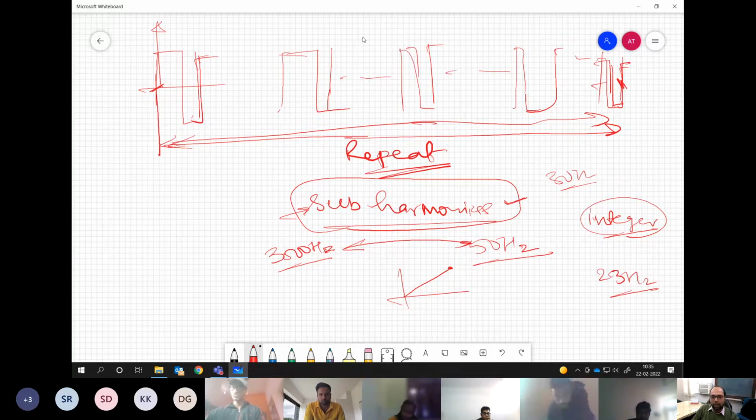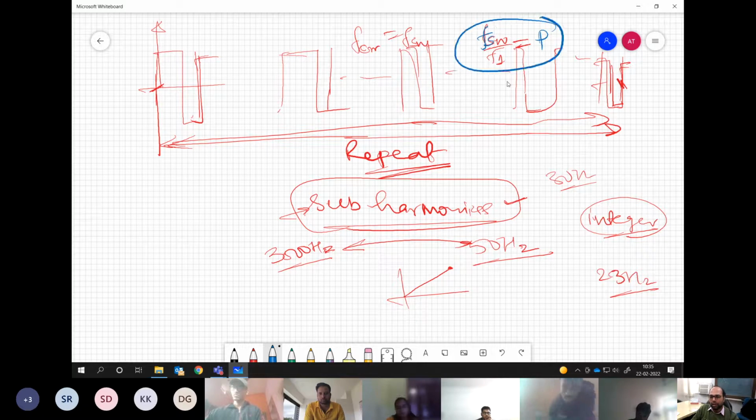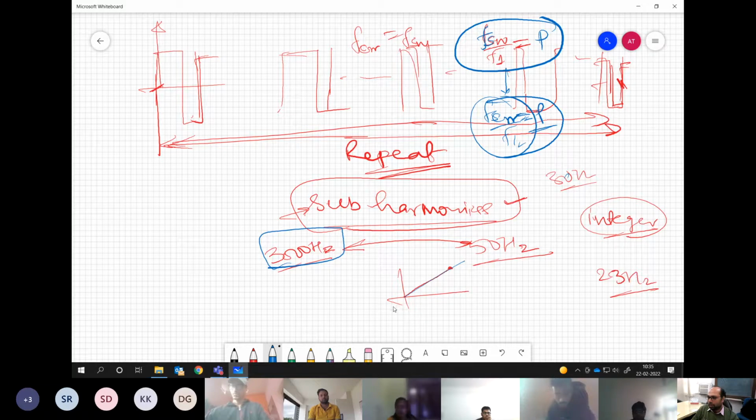So what is this ratio called, when we know that carrier frequency is the same as switching frequency? This ratio is called some name we have given, right? Sir, pulse number. Yes. So this pulse number is basically a ratio of carrier frequency and fundamental frequency in case of sine triangle PWM for a two level voltage source inverter. So this pulse number may be an integer, may not be an integer when you are running from 0 to 50 hertz, depending on how the ratio is coming out, you have constant switching frequency sine triangle.